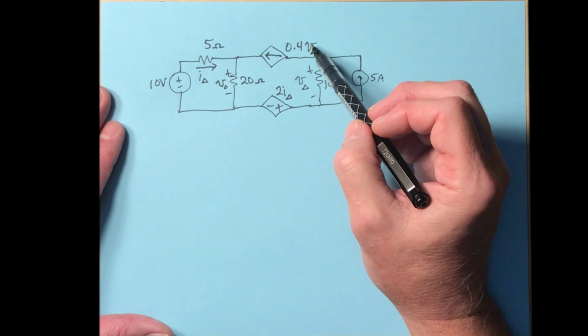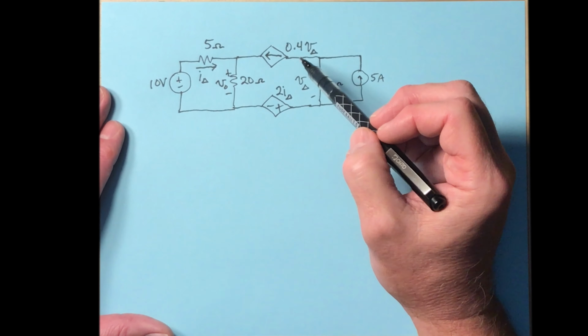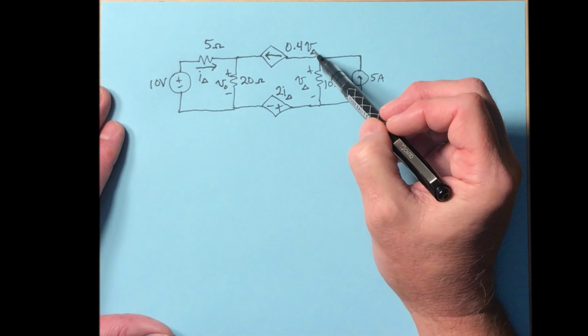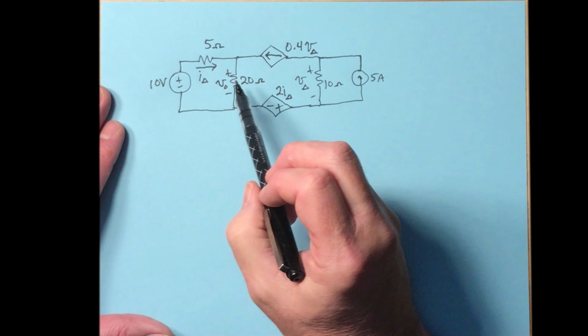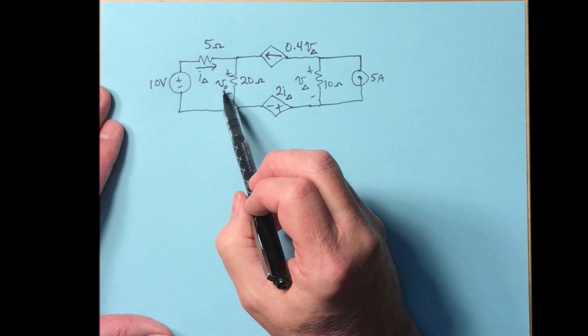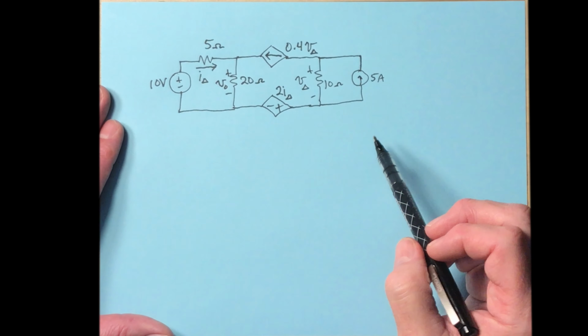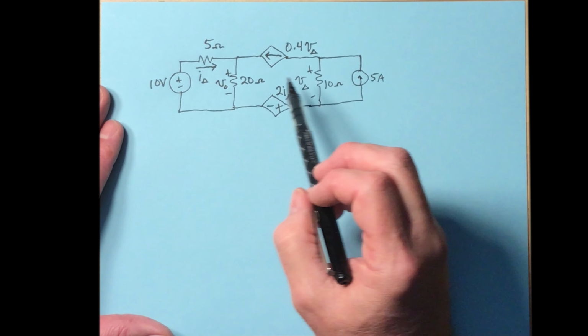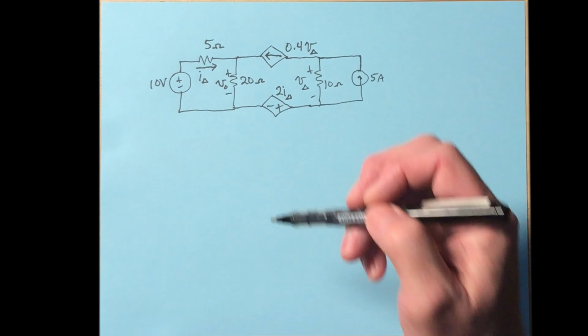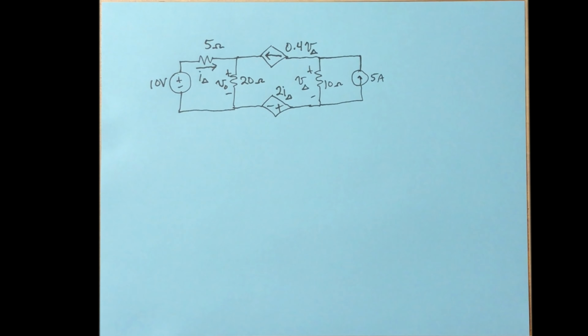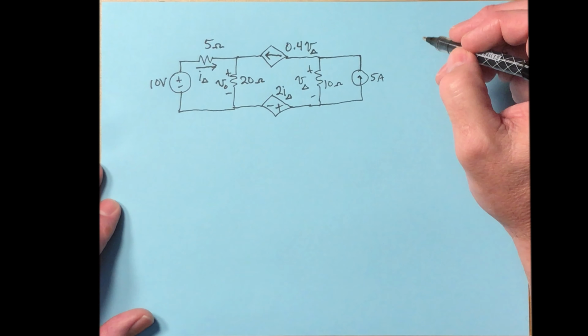And then we have a voltage controlled current source that's controlled by V delta, and you can see V delta is defined right here. But what we're after is V0. We need to find V0 using the principle of superposition. We can disable one at a time the two independent sources, but we have to leave the dependent sources there. All right, so let's begin.